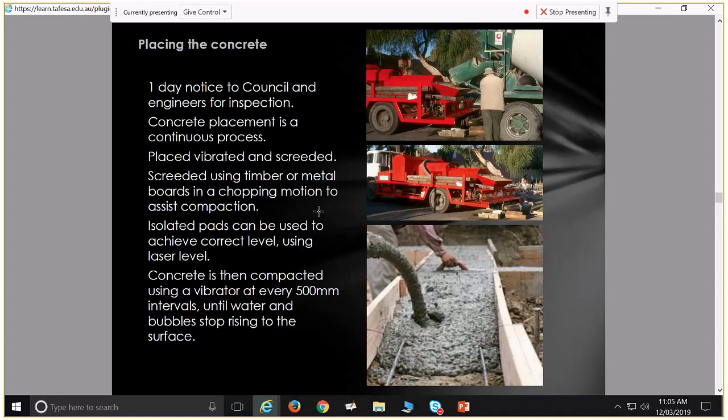That's where you just don't have enough sand or fine aggregates in the mix. But you also get that exact same effect if you don't vibrate the concrete down enough. You get all these air pockets in there. And with those air pockets, obviously you have significantly reduced strength. So if we've got some sections in there where the concrete hasn't been all vibrated down to remove all of that air, we just get sections where it's weak.